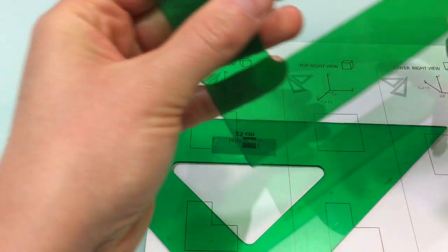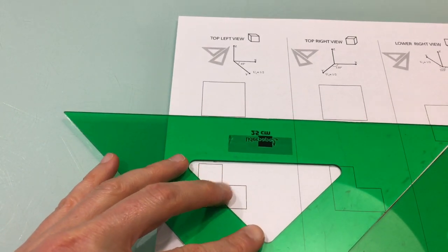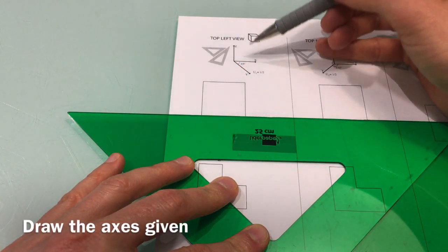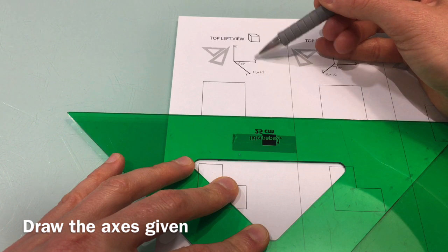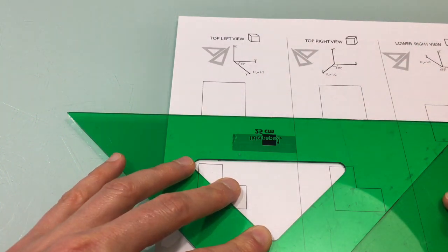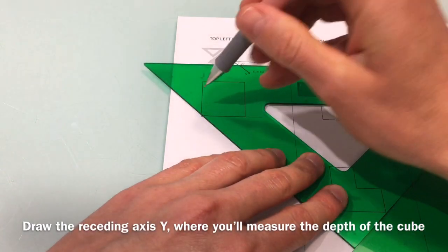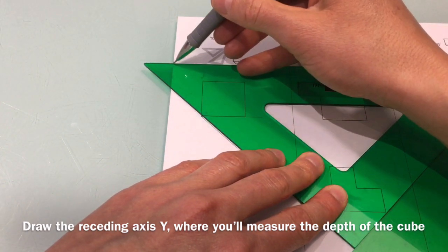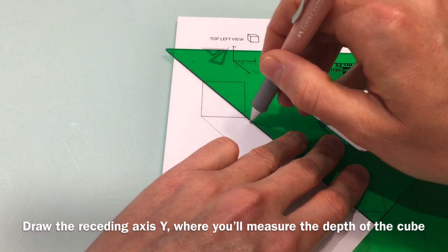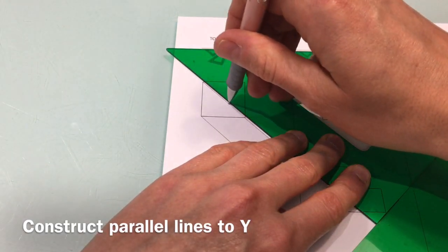We put the triangular set of squares in this position, and we will start constructing the axis. As you can see, the axes X and Z are perpendicular in all the positions of the cavalier perspective. Sliding the tool along the 30-60 degrees triangle in this direction, using the 45 degrees angle here, you draw parallel lines in the same direction at every single vertex of the rear face.